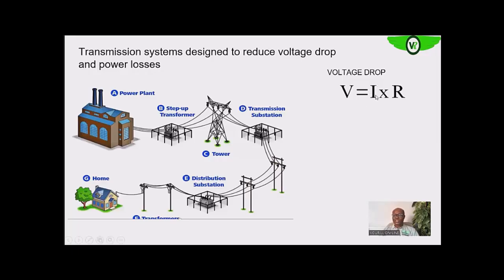So there are several ways we can do the reduction of this, but principally, we want to reduce this by increasing the voltage supply, that is, increasing the transmission voltage, I mean to say. You know, the power in the system is constant because the power in the system cannot be more than the power at the power plant. I know that power is a product of the voltage and the current on the system. So since this is constant, we can only play with V or I.